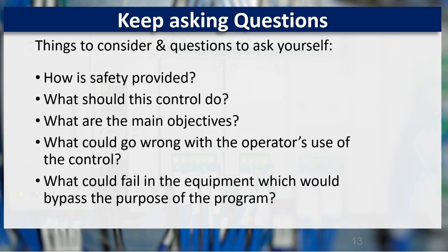Through this entire process, you should always keep asking questions. There's lots of things to consider and questions you need to have answered. How is safety provided? What should this control do? What are the main objectives? What would go wrong with the operator's use of the control? What could fail in the equipment which would bypass the purpose of the program?